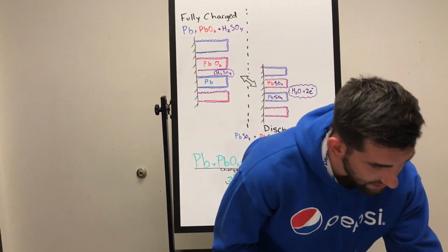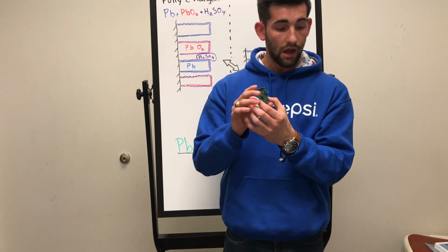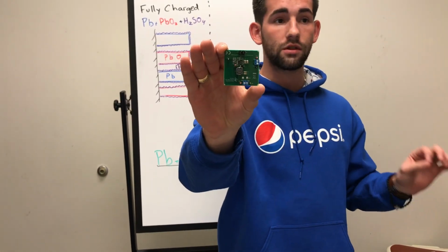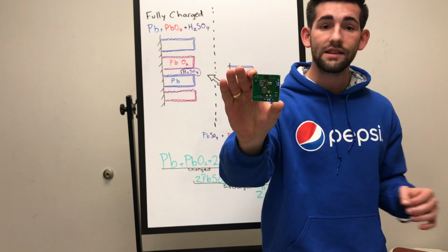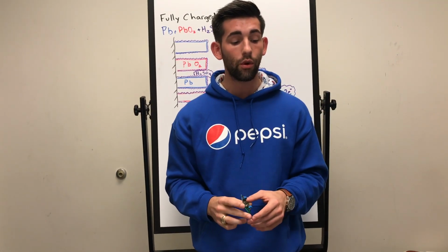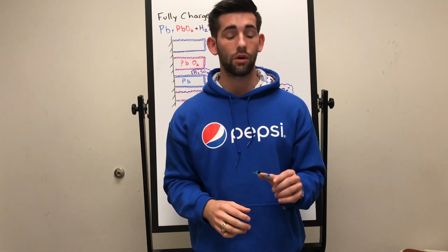And for example, this is a buck converter featuring the TPS54331 3-amp 7-volt to 28-volt input step-down DC to DC converter, which is used currently in my senior design project to power a 3.3-volt input single-board computer.